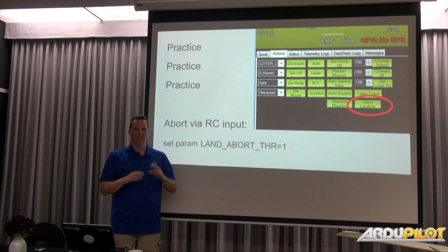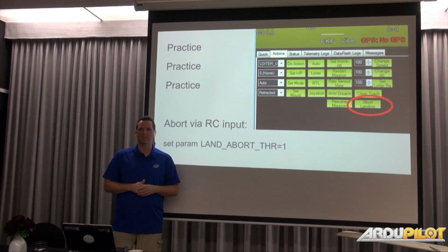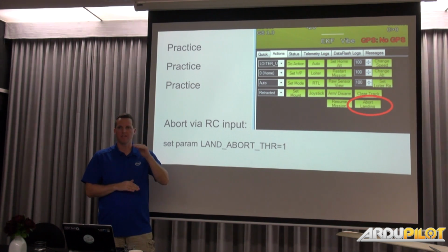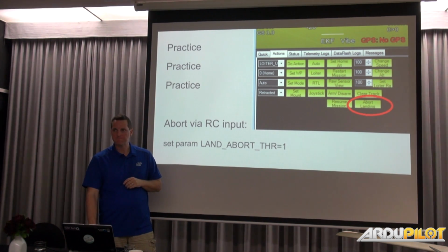Which happens on hour-long mapping missions and all that. It's very common to drift 5+ meters. And when you're trying to land and you're 5 meters off, it can get ugly. So that requires a LiDAR, some sort of correction to tell you that you're off that much.